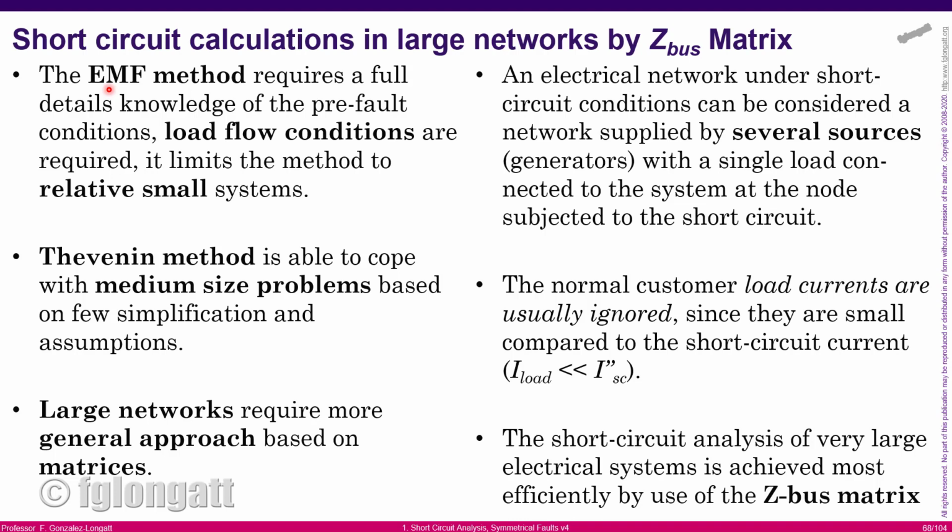Again, it's not my job here to discuss the method, but what we need to do is understand how to use those matrices. The first thing that you must understand is that for those calculations, usually we can neglect the load currents. That is what makes the calculations easy. Some other ways include the load conditions inside the matrices by including the effect on the voltages, but that is another story.